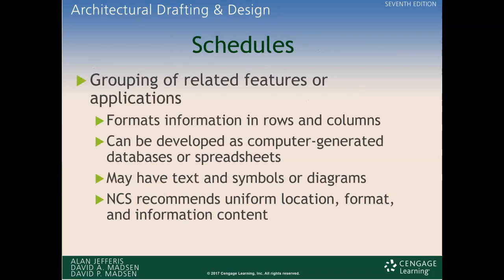Schedules should be grouped together to reveal their applications. A schedule formats information in rows and columns, just like in Excel. You develop them as computer-generated databases or spreadsheets, Excel, and they may have text or symbols and diagrams. And it should be in a uniform location among all the sheets that we're used to, usually at the lower left-hand corner.